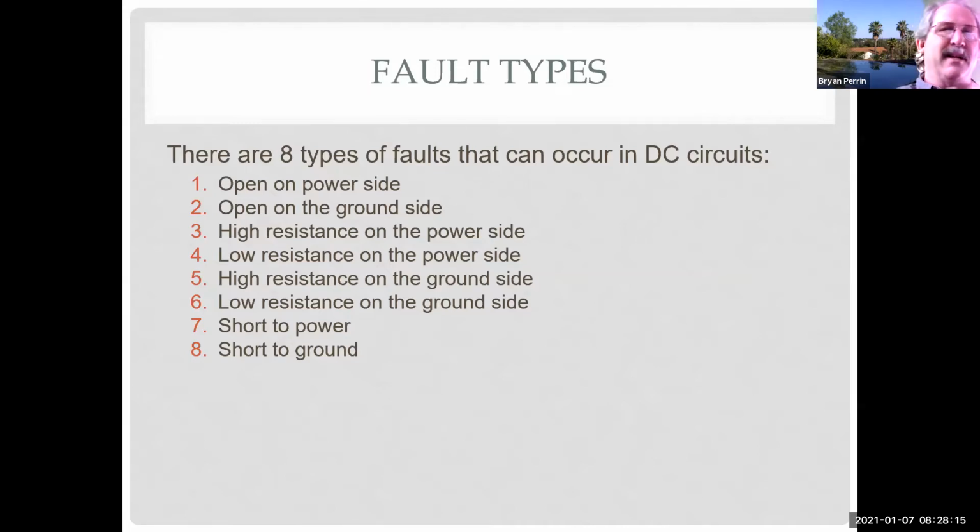If I have an open, it doesn't matter if it's on the power or ground side, we're going to diagnose it the same way. The only thing we diagnose differently is if it's a short to power or short to ground, because it's going to have different symptoms and we're going to diagnose it slightly different. But when you think about all the circuits and components on the car, a new car can have over 160 computers on it. And yet there's only 4 different electrical faults we'll ever need to diagnose.